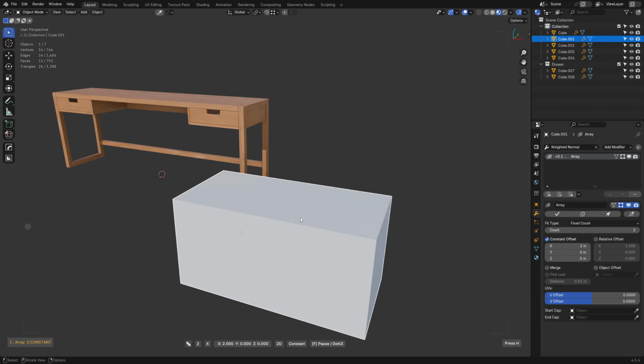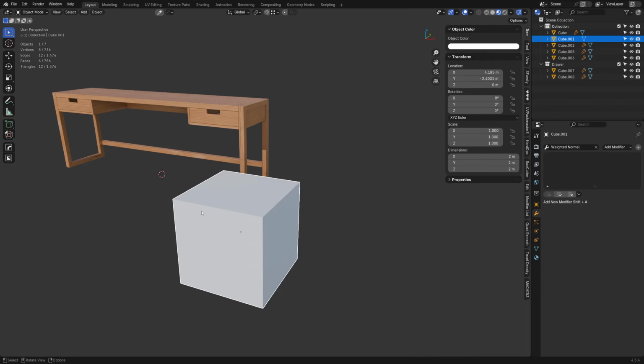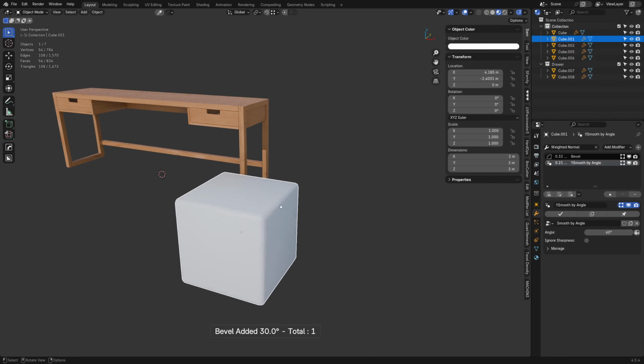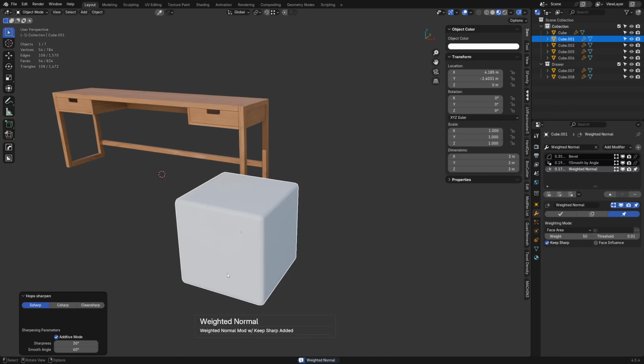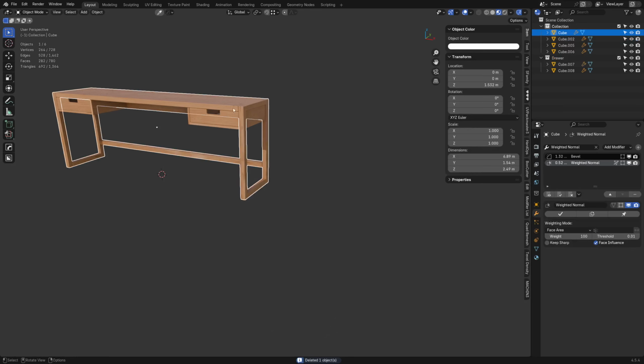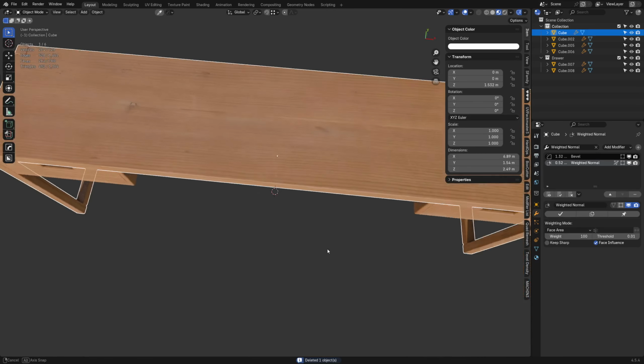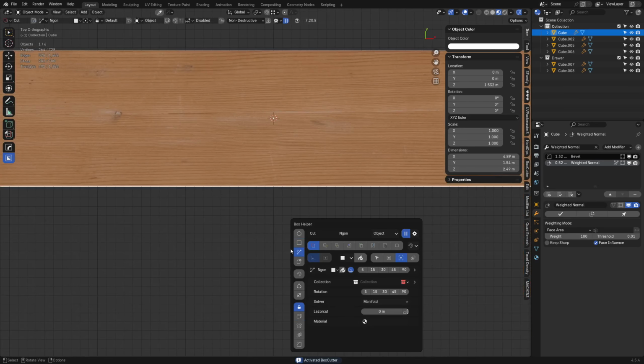You can literally hit Q and bevel, right? You don't go select the bevel modifier or anything like that. You want to weight the normals, you press Q, hold Alt, and hit sharpen. Boom. Weighted. So little things like that, very quick. And there's other little fun things you can do as well, like Box Cutter, for example. You can do boolean cuts.